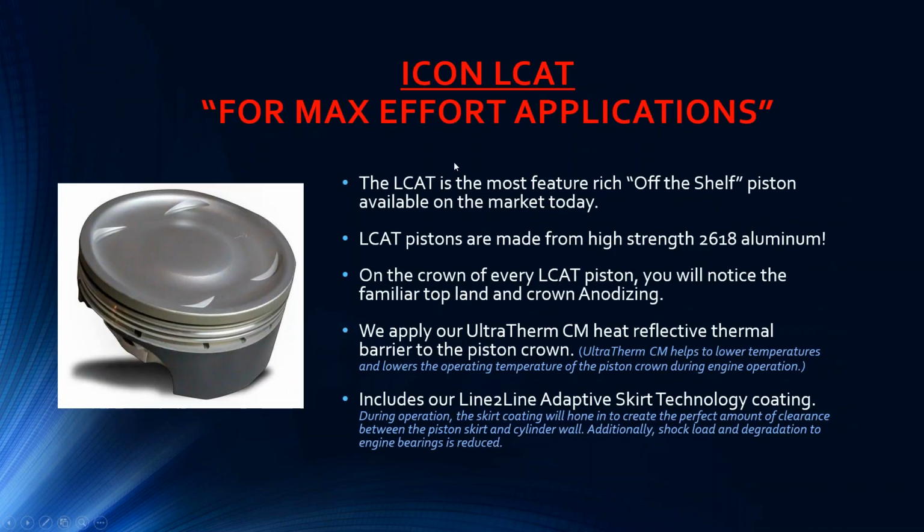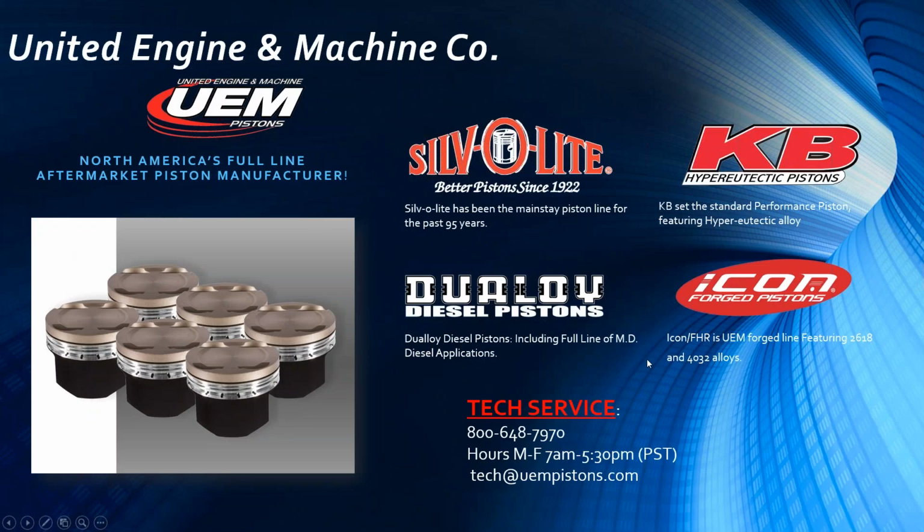And we also have gone one step further for some specialized applications. The real high output, we have the Icon LCAT, which has all those features and also adds the thermal barrier, ceramic metallic, as well as the anodizing and the adaptive skirt. So this is all available from us, and I've gone through that very quickly. I'm sure we have quite a few questions. I wanted to point out that for personalized individual attention, we have a terrific tech service department.